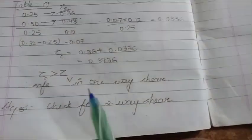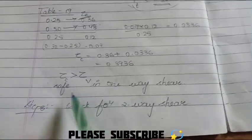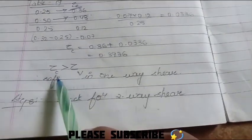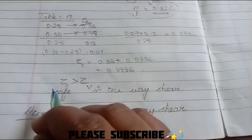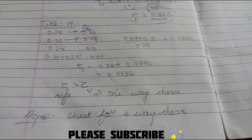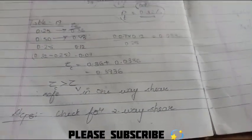Remember, the tau v value which we got over here should be less than the tau c, because this is the design shear strength value. Tau c is nothing but the design shear strength. Only if this condition is satisfied can we say the structure is safe in one-way shear. Only in that case we can say the structure is safe in one-way shear.